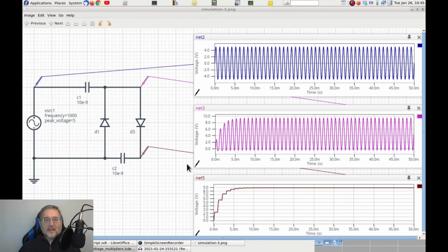If we now add another capacitor and another diode like this, we can extract at the end of the second capacitor a voltage that is almost constant, like you can see in this last diagram. And that is because the second diode operates like a rectifier and charges the capacitor C2 every time there is a positive crest in the sine wave. Note, however, how there is a small but still visible ripple superimposed to the DC voltage of the output.